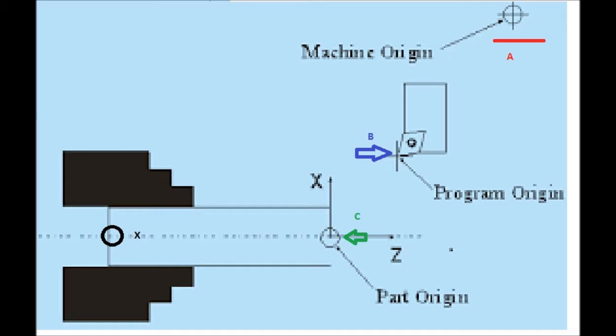The blue point, the B, is a new tool reference, which now includes the length of the tool we are using, because we want to be based on the point of the tool. Last but not least, there is the workpiece 0, and it's represented by the green point C down there, and it will be the base on which we will do all the work.